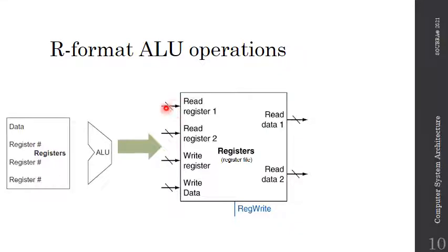All right. So here, and I'll pause the video again, I'm trying to find out in the buses and the arrows how many bits I have. Here it is the address of the first source register, and in the case of MIPS we have 32 registers, so the address should cover those. So: the address of the first source register, the second source register, and the destination register as well.